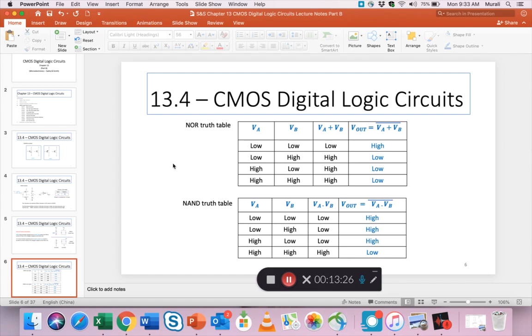Now that we have so many inverters, thousands, millions in our hands, we are not scared of NOR or NAND, because all we do is use one more inverter and we have the OR. But much of the theory that we'll study is built around using NOR functions and NAND functions rather than the OR function and the AND function. Okay, so just become comfortable with that.